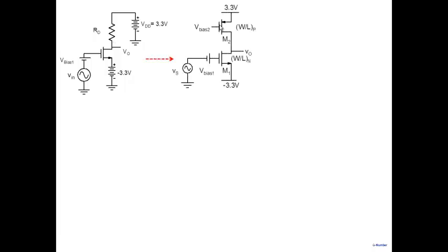All right. So if we think about now our MOS amplifier, this is our simplest MOS amplifier with a resistive load here. Now we know the problems with this particular stage, which is that the gain of this particular stage is low unless you make RD very large. And if you make RD very large, it becomes difficult to implement. So the solution to this one was, we saw, replace RD by a transistor. Right? So this is a better amplifier where you replace RD by a transistor, and now you can get large gain without requiring a very large value of resistor here.